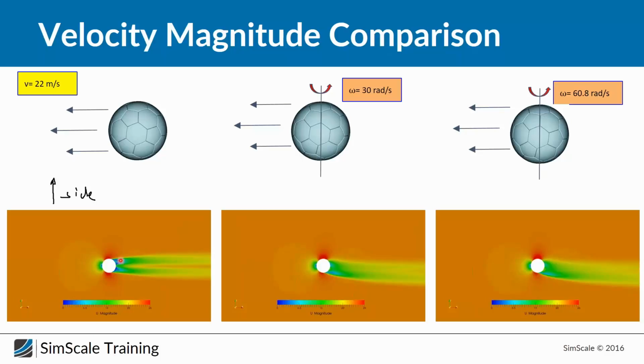And then we have here two dead water zones, which are a result of flow separation, and we have this diverging structure of wake, which is splitting up here. So we have these two vortices which are creating the structure here. And when we start to add rotation, first of all we can see two things. The first thing is, I hope you can see it because it's quite small here, that the stagnation point changed the structure a little bit, became thinner. And what is also happening, and this is more important, the wake has changed.